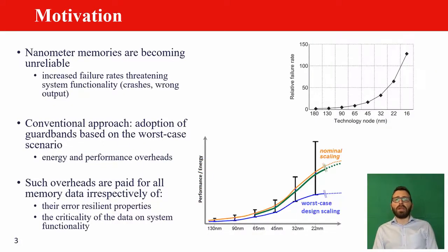However, memory is rendered even more susceptible to errors at lower nanometer technologies. To retain the same reliability, manufacturers adopt pessimistic guardbands. This approach hurts both the performance and the energy consumption of the memories. Those guardbands are selected based on the worst-case condition that the chip can experience, which may rarely occur in normal operation. Furthermore, by applying the same guardbands across all the memory chips, they ignore the fact that there can be a great variability of the reliability of each device.